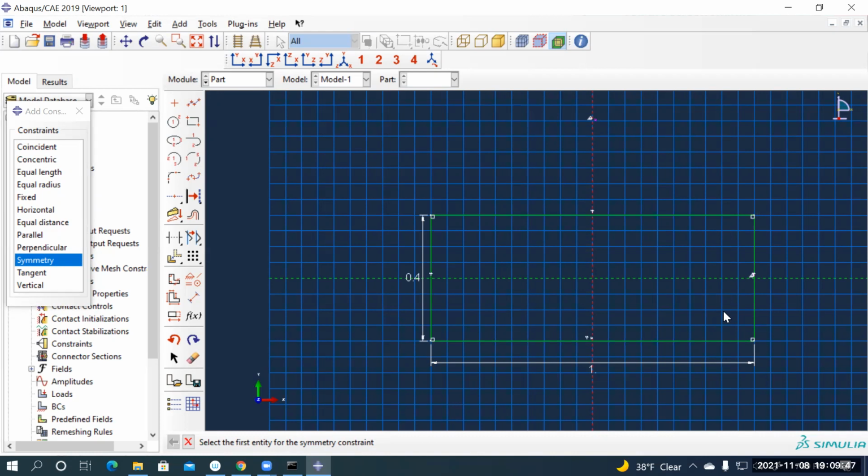Everything's defined, and the center of that rectangle is the origin. It's important to do that because in the next steps I'll be creating the same sketch again, and the origin will be my reference for all the sketches I'm going to put in the different planes. Everyone's able to do that? Do you have the rectangle in green?